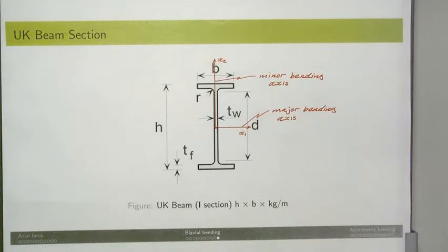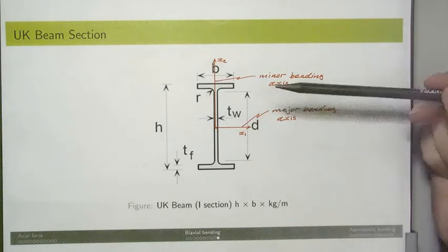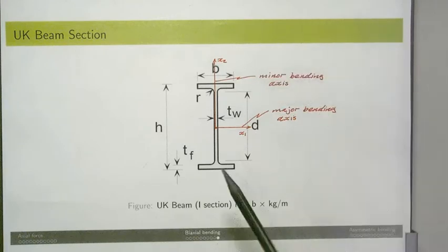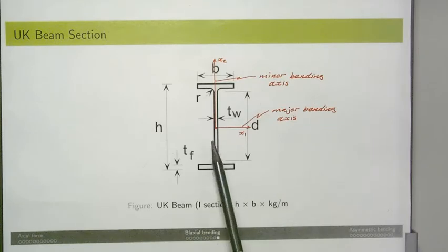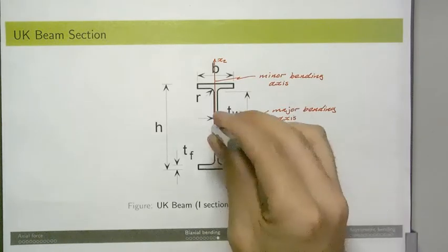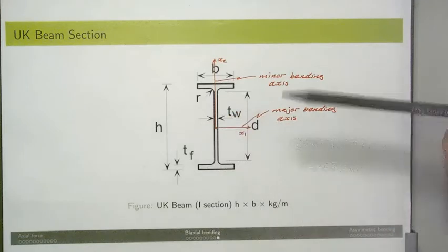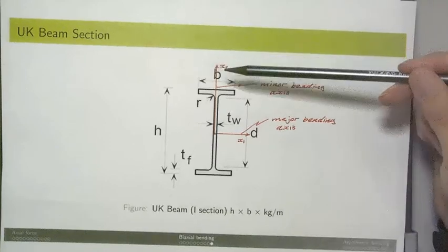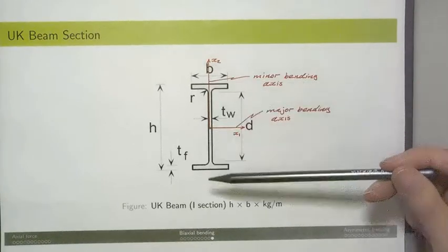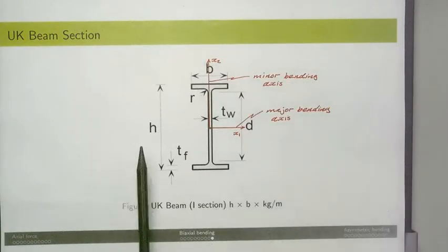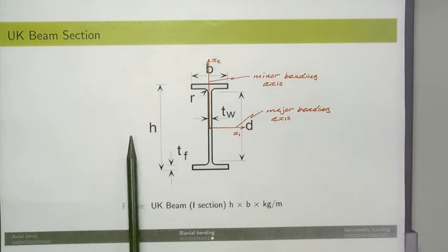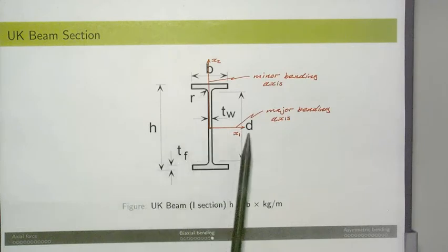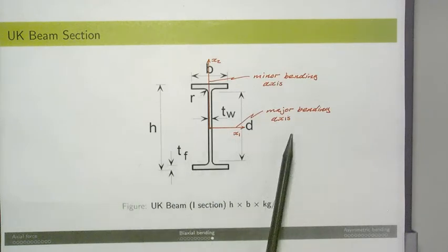So if we imagine that we've taken a cut through our simply supported beam, so effectively the x3 axis is coming out of the page towards us like so, so just coming straight up in this direction, then the loading that we've been told about, so we have a distributed load that's going to be acting down in the x2 direction, and we also have a distributed load that, as said, is acting on the left hand side of the beam in the positive x1 direction, so that's going to be coming across and acting in this direction like so.